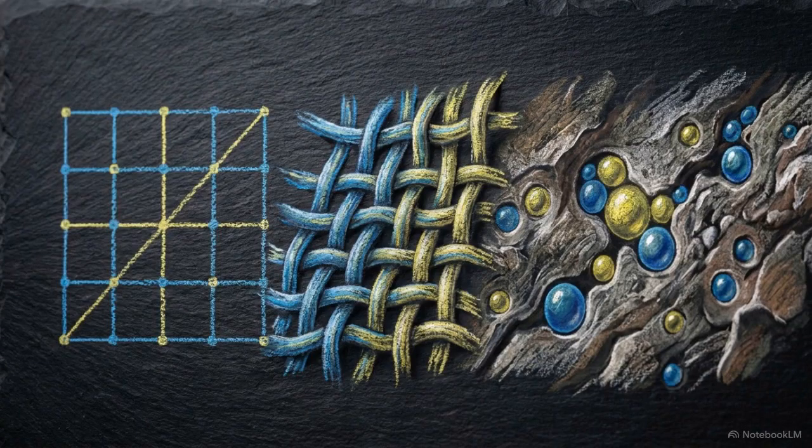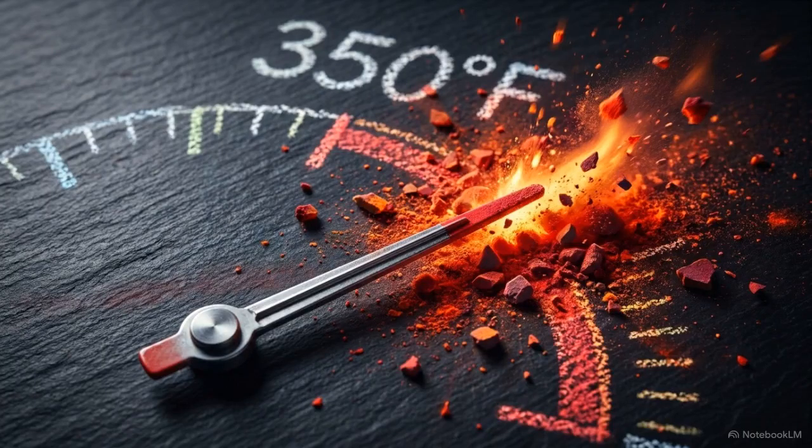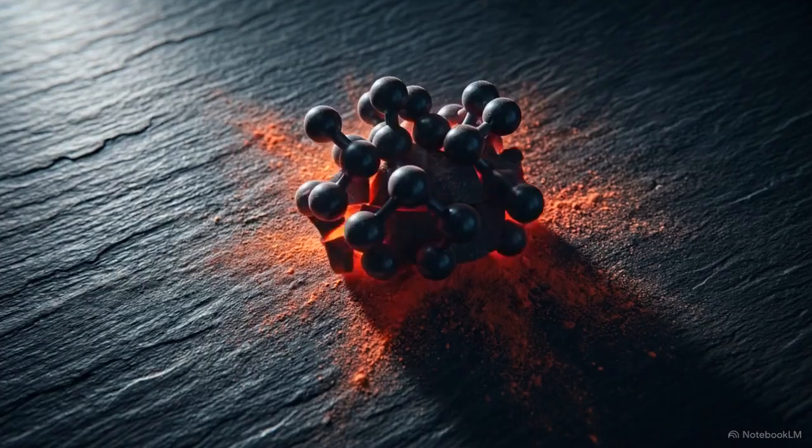Surviving reactive shales requires layering three distinct defenses: geometric crystalline locks, physical polymer wrapping, and thermally activated emulsion barriers. At the deepest stages of the wellbore, temperatures cross the 350-degree Fahrenheit threshold, entering the extreme high-temperature, high-pressure regime. Traditional water-based mechanics fail here.